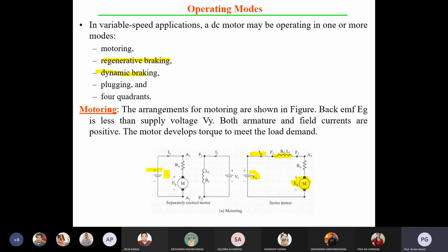Okay, so you will replace that source voltage by a resistor. You know that in traction motors there is a shunting resistance, and that shunting resistance may work in different manners. Suppose it is used as an additional resistance in series with your armature. So it's a series motor, and that same resistance is working for the dissipation of the energy.